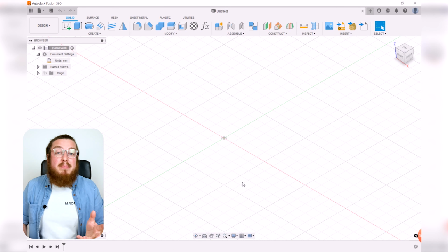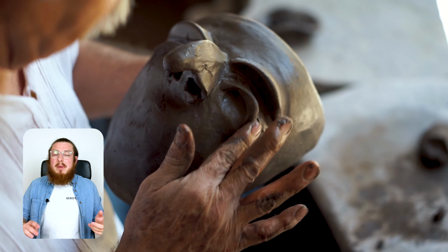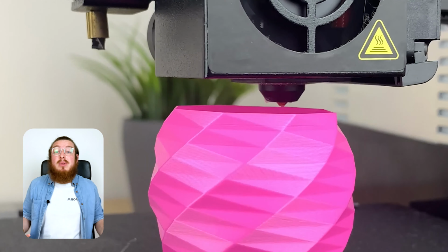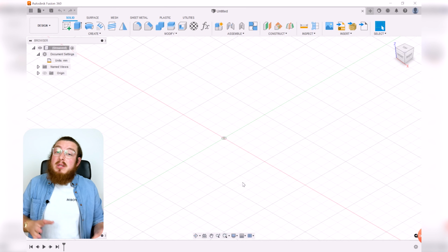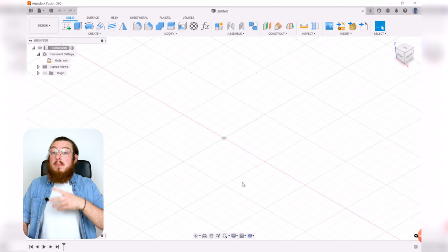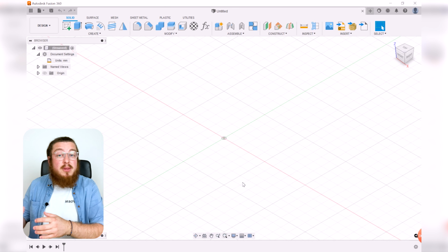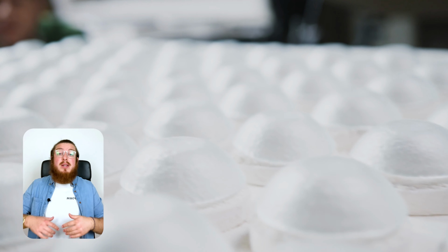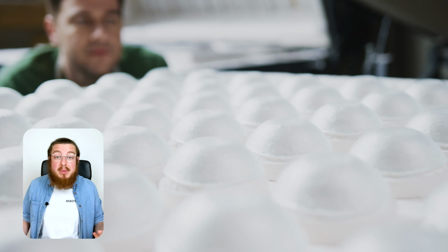So throughout the molding process, you'll always be starting off with your initial material. It's usually called a buck, and it can be made from clay, wood, 3D printed material, anything you'd like. But very often through the molding process, you either want to have a really hard material or a completely different material than what you started off with, or you'd like to have some of the reproducibility if you're going to go into a manufacturing process for a business.